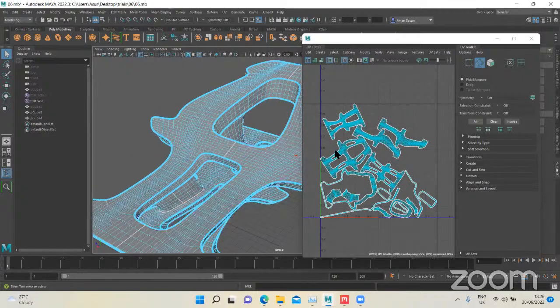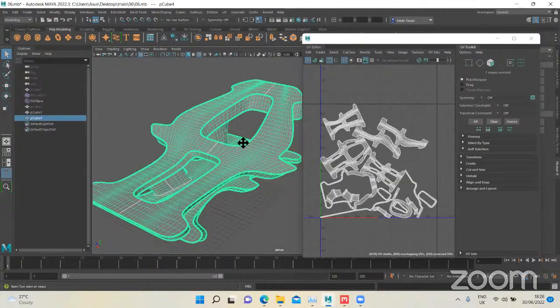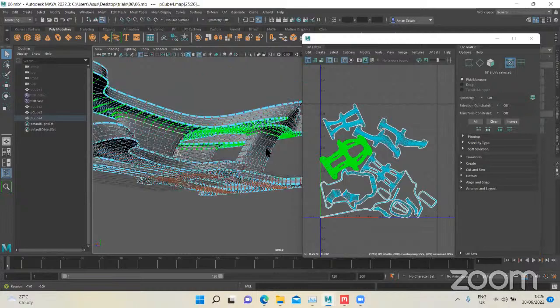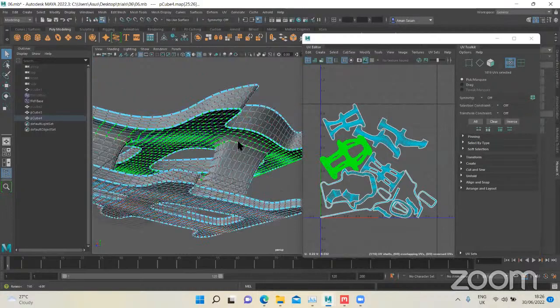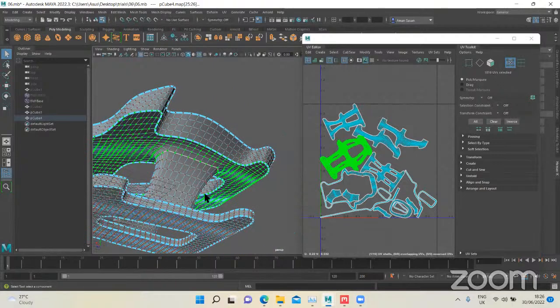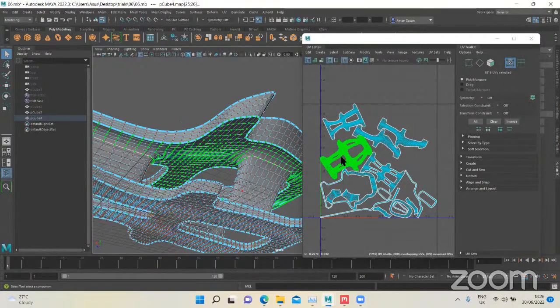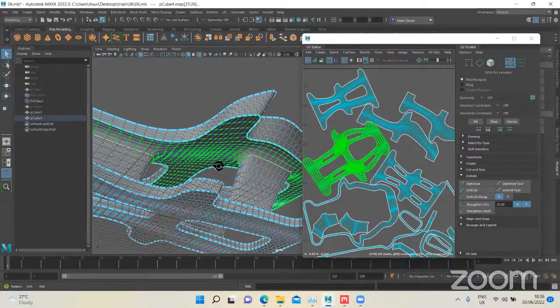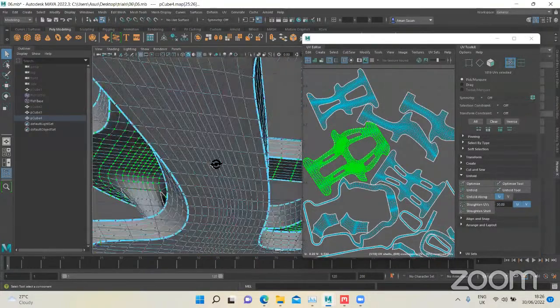Okay, so coming back to mapping. This model I completely UV mapped. As you see, all these portions where I thought I have seams, so I have seams on this edge. I selected the whole edge loop, cut out this area, and used the unfolding. It basically gave me a pretty good shape.